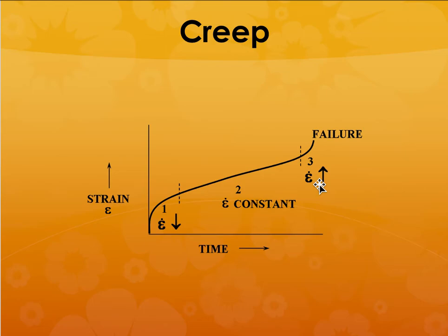And what is that magical temperature beyond which creep processes will start affecting your component? Just like the differentiation between hot working and cold working, it is the same temperature.